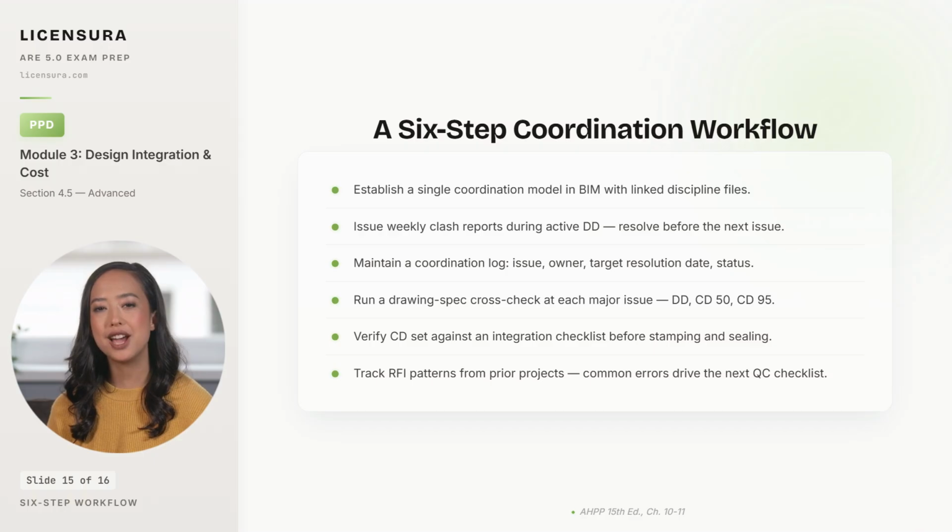Fifth, verify the CD set against an integration checklist before stamping and sealing. Once stamped, the architect owns the documents under licensure law, and the stamp is also the trigger for personal liability if the documents fail. Sixth, track RFI patterns from prior projects, because the firm's most common errors should drive the next project's QC checklist.